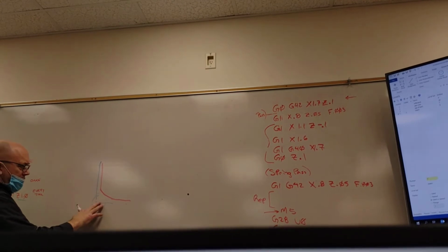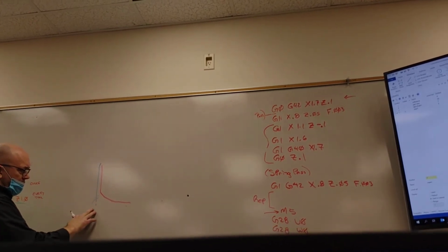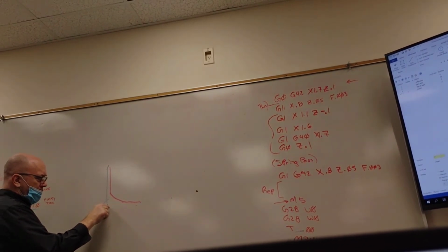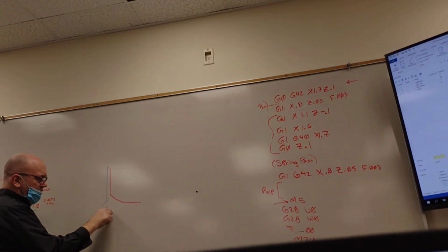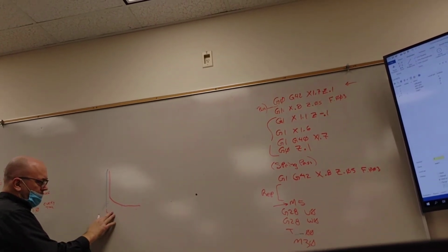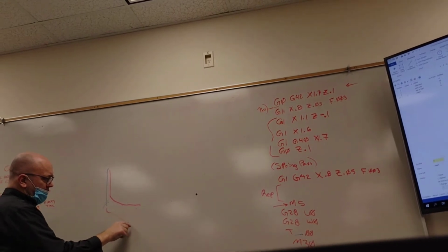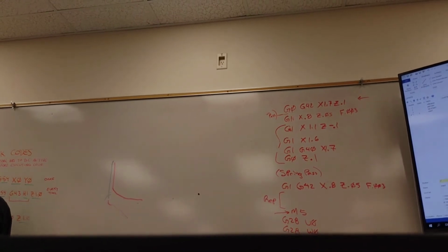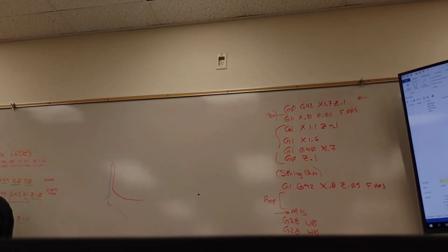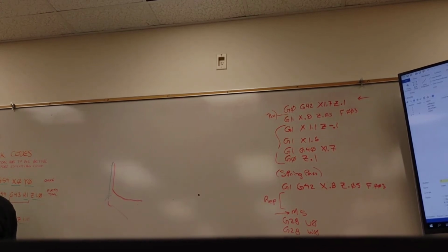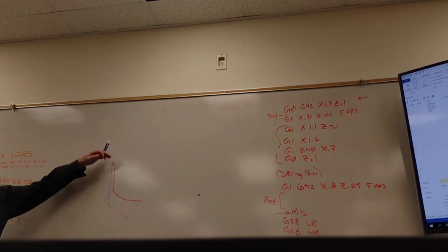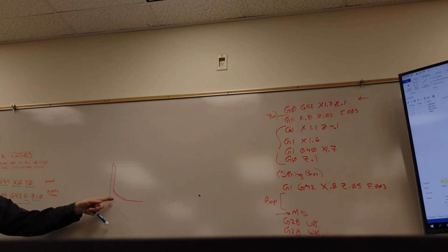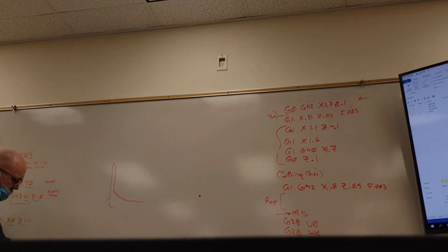You're likely to, if we drilled this, if all we did is drill this, or drill it and maybe bore it, we'd probably end up with a little bit of a fillet, and then possibly a taper to where our drill point went to. Does that make sense? So we're going to have to do a little fitment test. We're going to have to fit our part in there and do some calculations to determine how the top of the part fits to our body. But the important point here is we want to make sure we have some clearance.